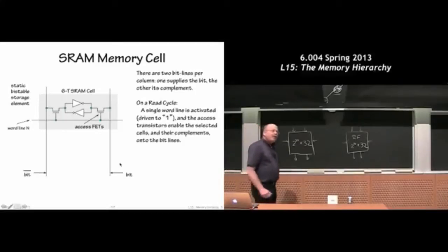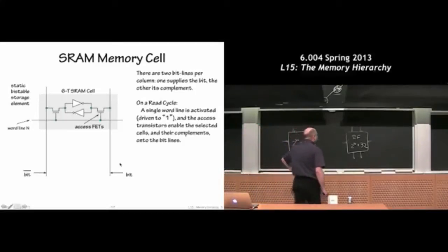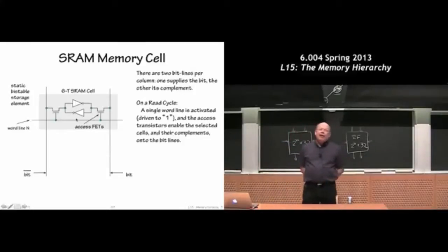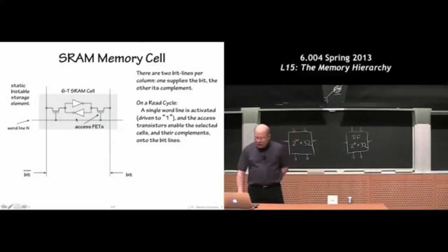Okay, so first up on the list is the technology that we're using inside of our register file, a so-called static RAM. And at the heart of the static RAM, I hope you recognize that diagram. It's a little bistable loop made by a little loop of inverters. And that loop will reliably remember a value. So if I have a 0 on one side, I'll have a 1 on the other side of this little loop, the other side being the other of the two nodes.